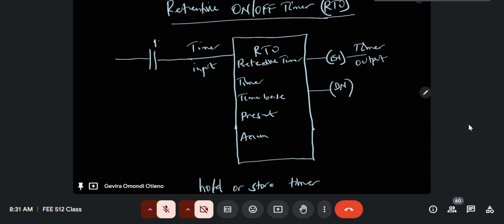So it gives a logic high to the timer, so the timer works. If this state changes to 0, then it's equivalent to the timer not working, because the timer is deactivated. When the timer is deactivated, we don't lose this value because we store it or we hold on to it. So that when this changes back to logic 1, we can continue our count as usual.